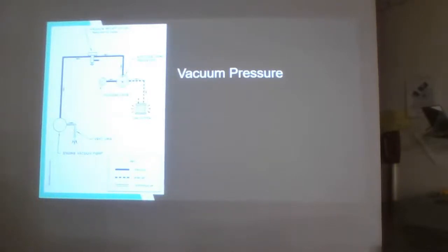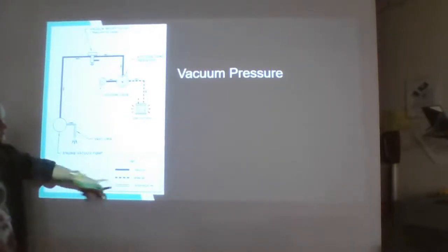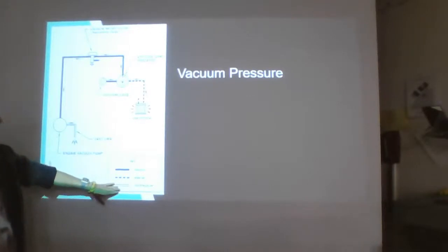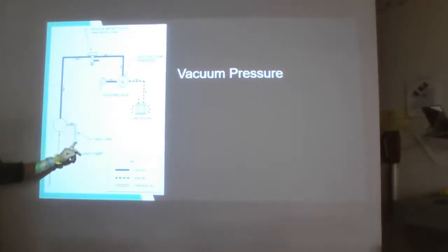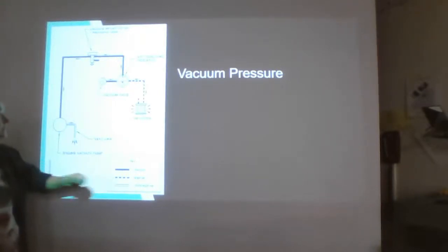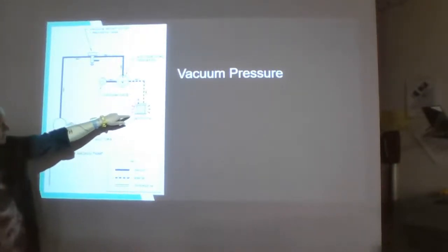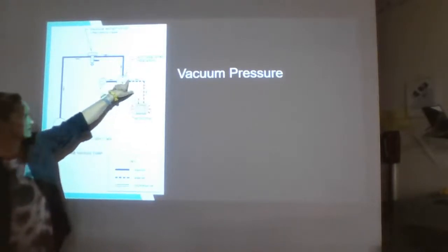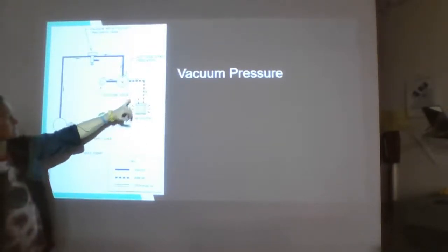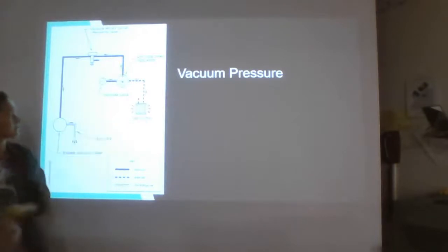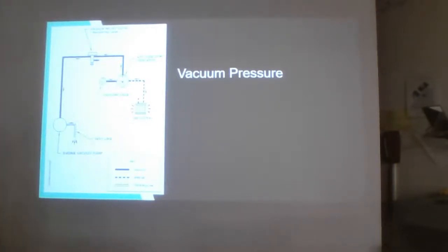And you have your key down here. I don't know if you can see that, but this double line, such as right here for the vent, represents discharge air. So in the vent line, it's discharging any unused air. The dash line, such as for the filter, is your inlet air. So like I said, we have air coming in that is filtered through our instrument air filter. You will change a lot of instrument air filters. They're due every so many hours.